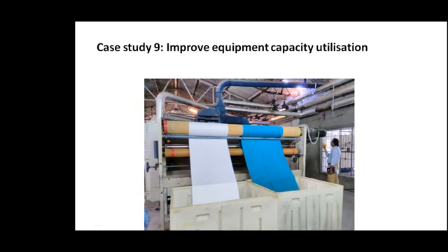So here again, the same capacity utilization concept. You see this entire width of the stenter in a textile mill. The stenter is another kind of drying equipment. So here the cloth goes inside this chamber. About 5 chambers will be there, and then hot air is blown, thermic fluid supplied. So hot air is there inside the chamber.